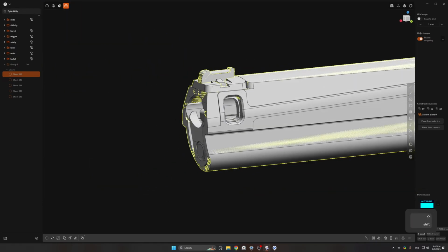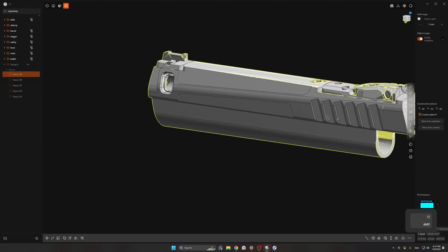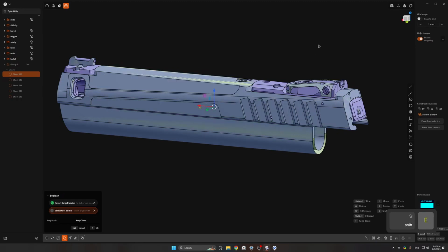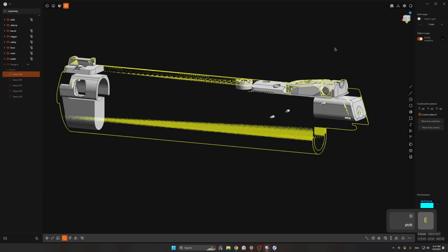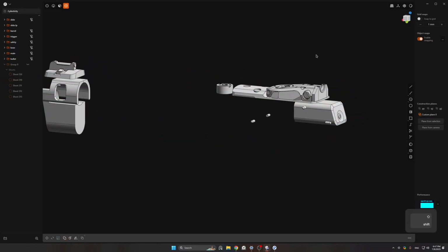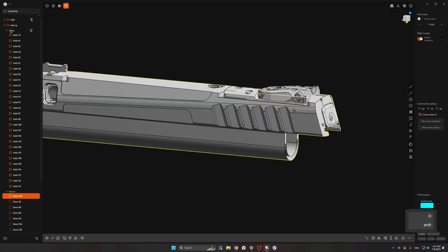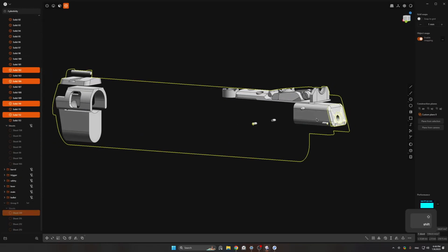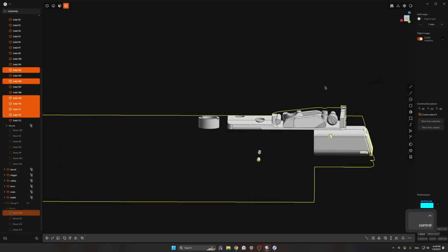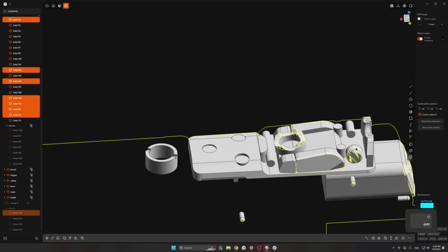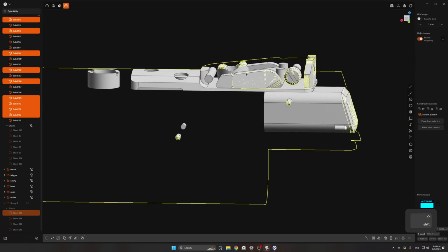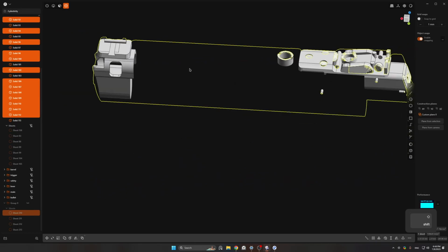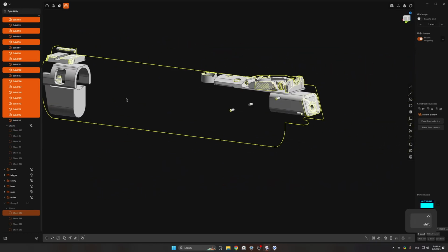After that, we're gonna press Q for boolean, then Shift E for intersect, and then we're gonna confirm it. And this will create our outer shells. Let's disable all the sheets in the folder of the slide and put the original sheet body into the folder, because it now is one of the details. And let's just continue the process until there is nothing left.